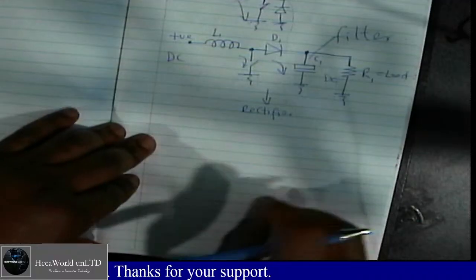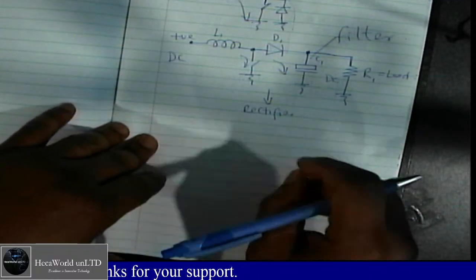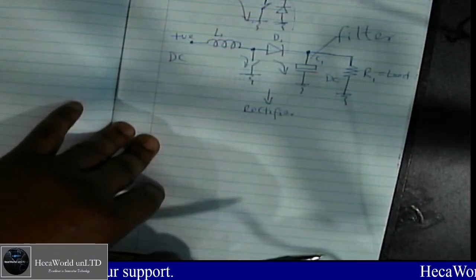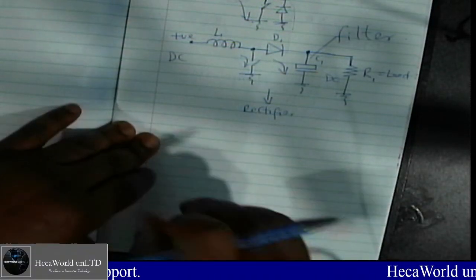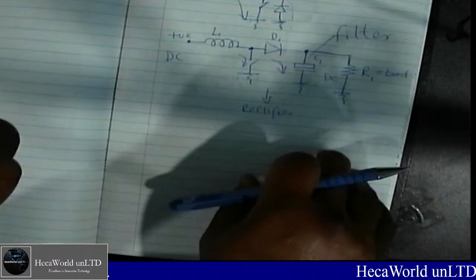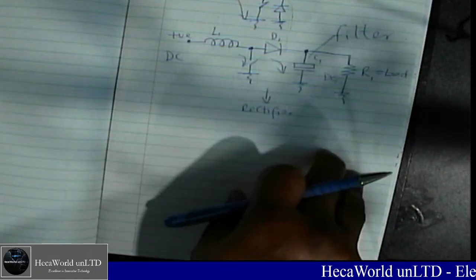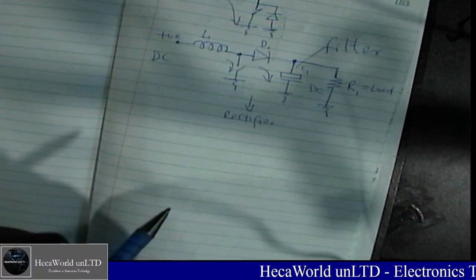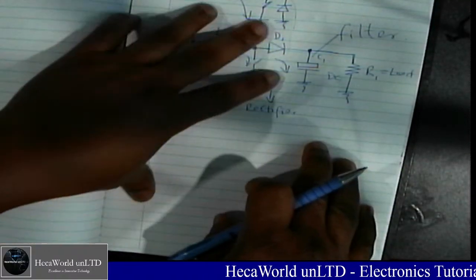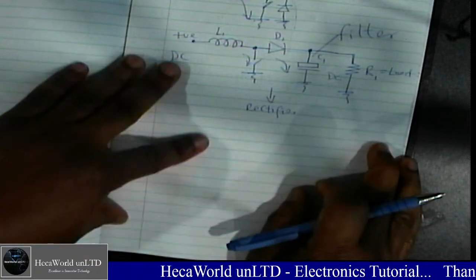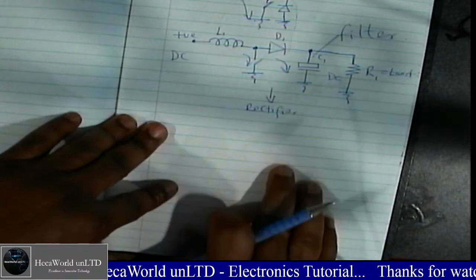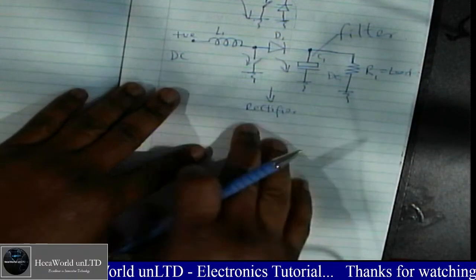Because we want to be able to control the pulse width a little bit, and MOSFETs do better than regular bipolar transistors. The gate resistance is very low, and it can handle very fast switching. It can sink or source more current than many regular transistors. So we're going to use a MOSFET today.